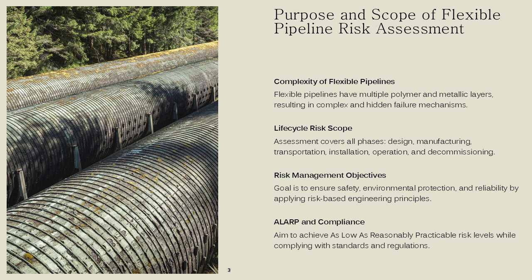The purpose is to ensure safety, environmental protection, and operational reliability by applying risk-based engineering principles aligned with API RP17B guidelines. This involves integrating hazard identification, consequence analysis, and preventive measures into decision-making processes. By focusing on life cycle risks, engineers can anticipate degradation mechanisms, validate design assumptions, and implement monitoring strategies that reduce uncertainty. Ultimately, the goal is to achieve ALARP, as low as reasonably practicable, risk levels while maintaining compliance with industry standards and regulatory requirements.